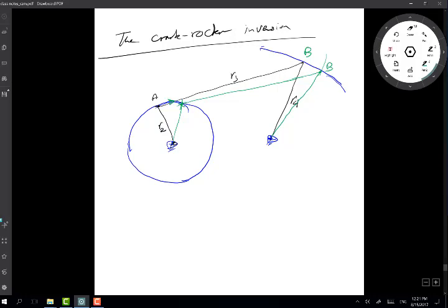All right, so what I want to find now is how far point B is going to go in this direction, because we agreed link R4 is a rocker, so it rocks between two different positions. So I want to find the extreme position of this link, or what some other authors call the stationary position, because it will go to this position and stop momentarily before it starts coming back and rocks to the other direction, to another extreme position. So I want to find this stationary or extreme position on the right hand side.